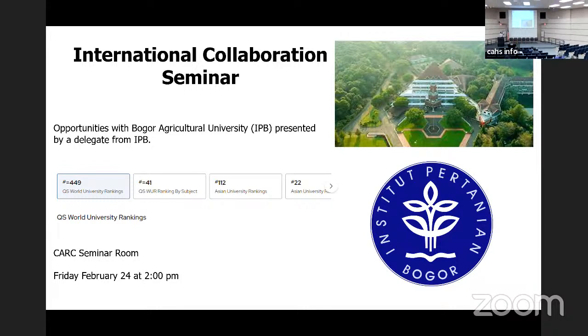So if we can reduce the movement of water through this moisture barrier, then most of the water from the rainfall will go as runoff, and it will accumulate at the toe of the slope. Now they put a high capacity drainage system there, so that no moisture accumulation occurs at the edge of the slope, and it doesn't create this kind of cracks. Typically they use this kind of asphalt patching. Now with more and more vulnerability because of the environmental conditions, this patching is not enough nowadays. They are trying to use different methodologies.